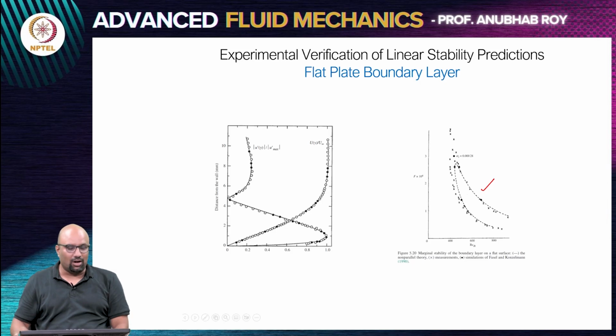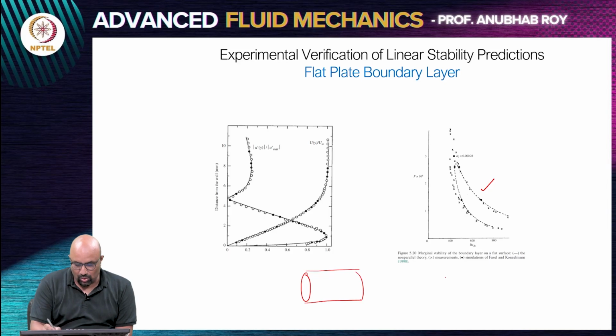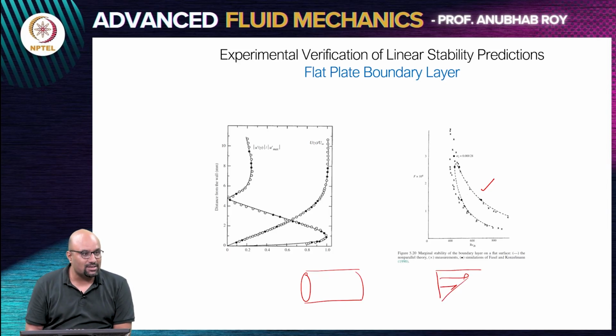This is obviously not the complete story, and as I have been repeating, it's not possible to summarize all that complete story, because whatever I have said here is based on that theory, two very simple problems: flow through a pipe and a Couette flow. We have done these in class. Based on all the linear stability calculations we did using normal modes, these two problems are stable. There is no instability.